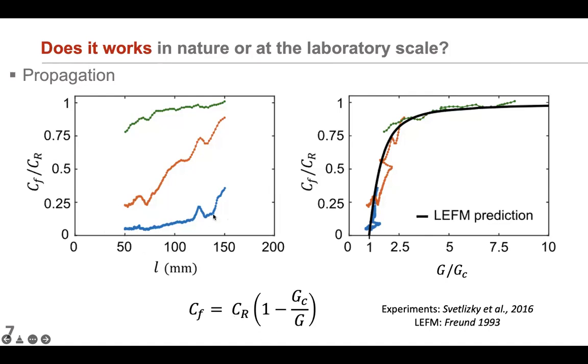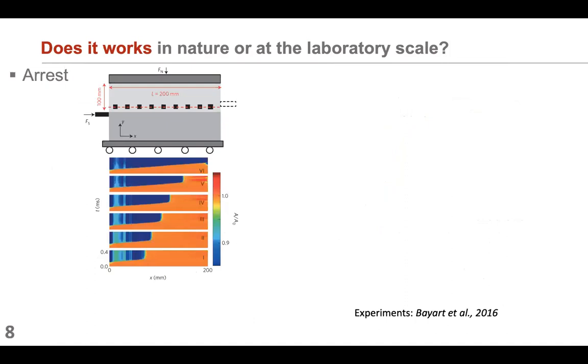And you can see that using LEFM, linear elastic fracture mechanics, they were able to show that knowing both the energy release rate along the fault plane during the rupture propagation and the fracture energy, they were able to predict the evolution of rupture speed as a function of the distance to the nucleation point. So the final point that I wanted to address is the rupture arrest.